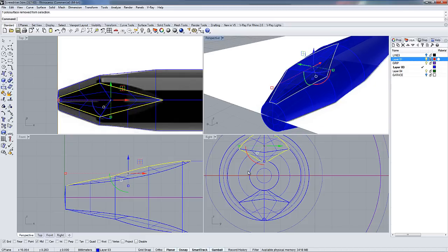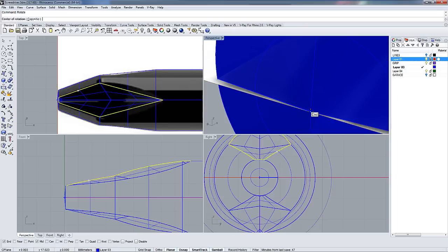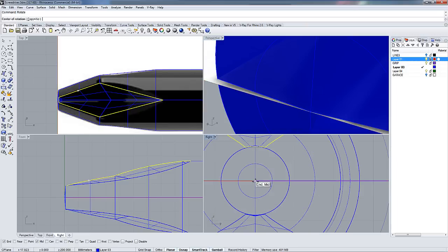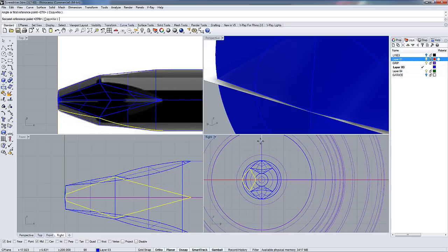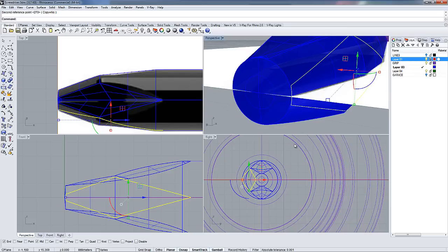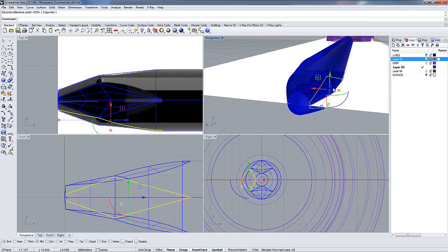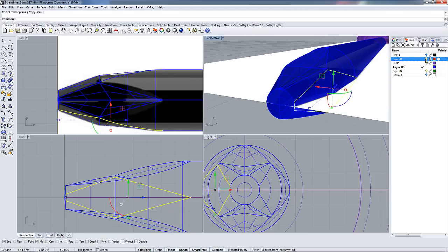So select the lines at the top and right rotate. And at the right view, or at the perspective, select the mid or end point of the screwdriver and press shift so you can turn it 90 degrees. Now you have the line at the right view, right side, and now you can mirror it from the end point. And again shift.